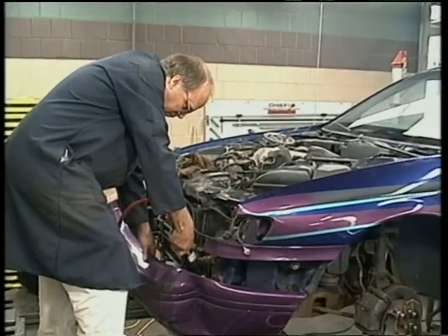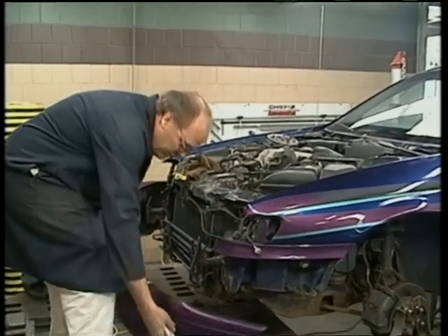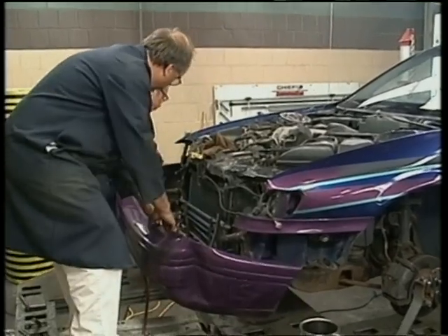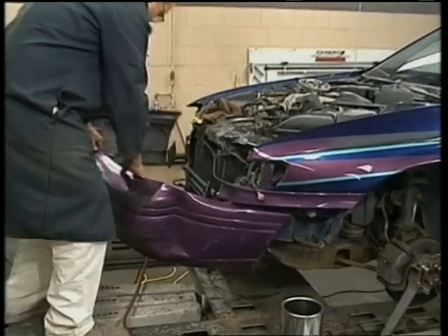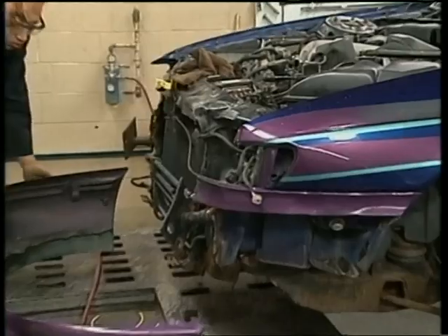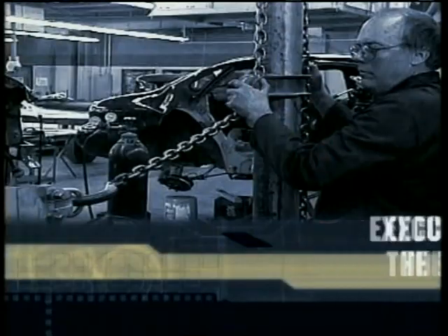When beginning a pull, remove only the parts that prevent you from getting to an area you need to use for the pull. Avoid removing weld-on parts unless absolutely necessary. When planning a pull, remember that a single hard pull will result in tearing of the metal before straightening occurs. Most work will require multiple pulls to correct the alignment problem.